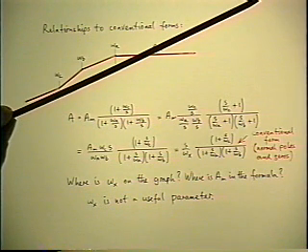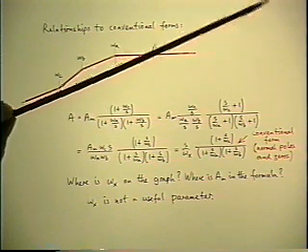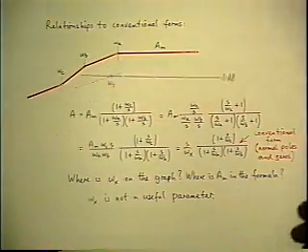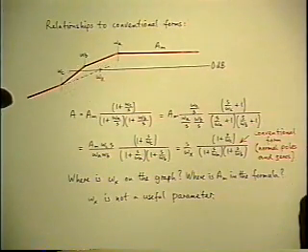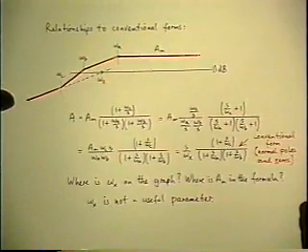This is a special case of that. Right. Omega x is the frequency where the zero frequency asymptote crosses 0 dB, or unity gain magnitude. So I could draw it like that.